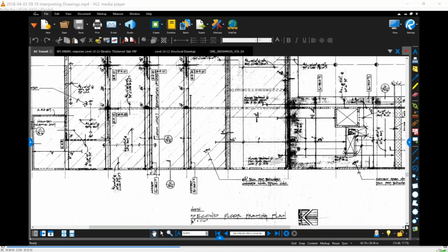So one of the things we were showing on here was the tendon profile, where you have spans, and they show in the middle. It was like 1 inch. 1 inch, and so this is the distance from the bottom of the slab. And then what would it be here? 7 1/4. Seven and a quarter inch.